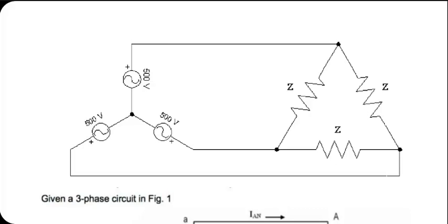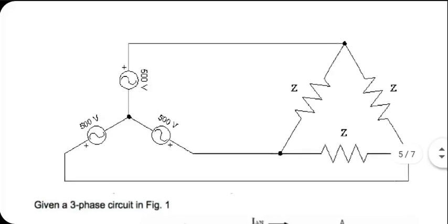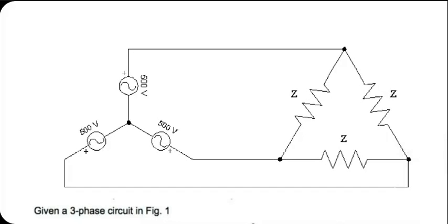And by the way, books do not mention it generally. Besides the neutral wire, there's a fifth wire also sometimes. It is known as ground wire. Neutral in theory can have zero voltage if everything is balanced. That means all arms of the load have identical impedance. All generators have equal output voltage, equal frequency, etc. But that is very difficult to predict in real life. In reality, the neutral may not always be at zero potential. I'll prove it all mathematically later.